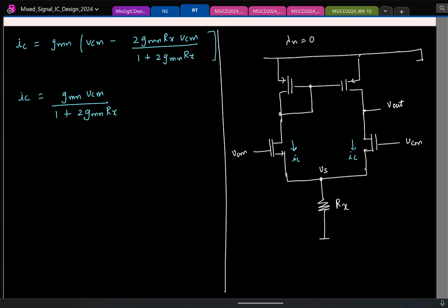So now let's quickly look at small signal voltages. Let us say I'll try to find this voltage here, V3. So what is the resistance looking here, R3? 1 over GM of which transistor? Is that fine? Gate and drain are connected, so any excitation you apply at the drain gets connected to the gate, so GM times the gate voltage gets drawn. So the impedance is 1 by GM of the PMOS.